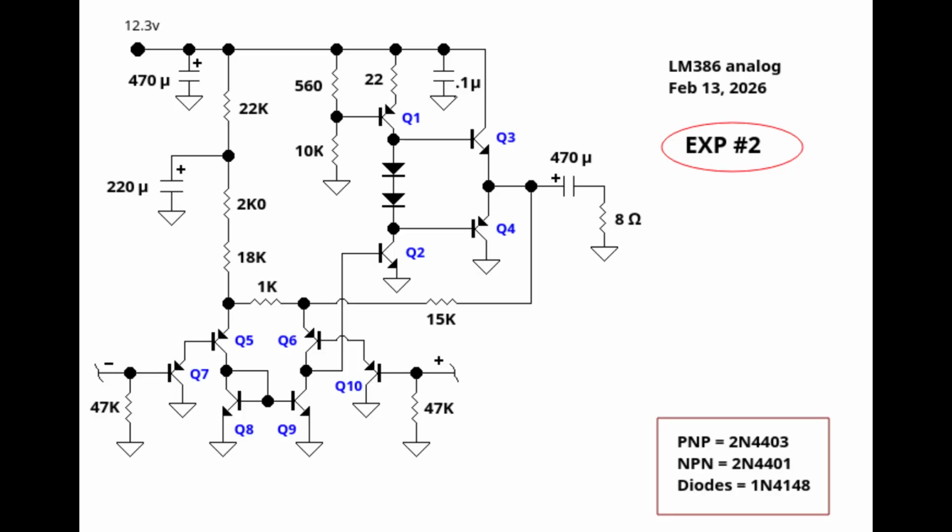Well, the main problem is that the LM386 design is limited to a low voltage single DC supply. Within this limitation, in order to get a power amp output signal swinging as close to the DC rails as possible, you must depart from the bog standard complementary pair of emitter followers. Why, you may ask?